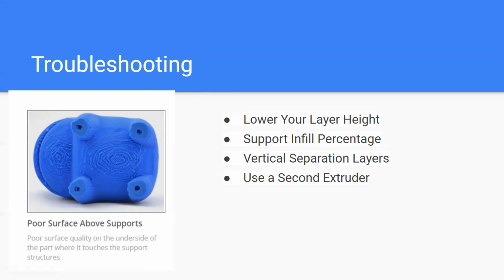As well, a little bit more about our support infill percentage. So we talked about using 25% for regular infill percentage. Usually support uses around 20 to 40%, but its density is lower there. You could increase this above 40% if you wanted to, if you notice this early on. If you do it later on, your support's just going to become top heavy and not be effective. It's just going to fall over. So you've got to notice that early on to do that.